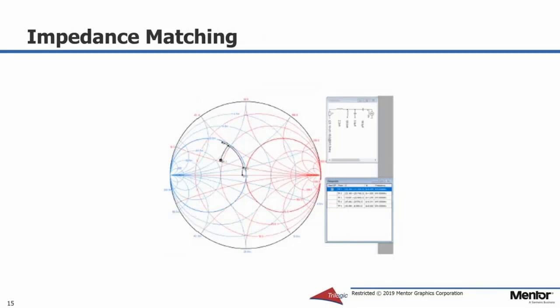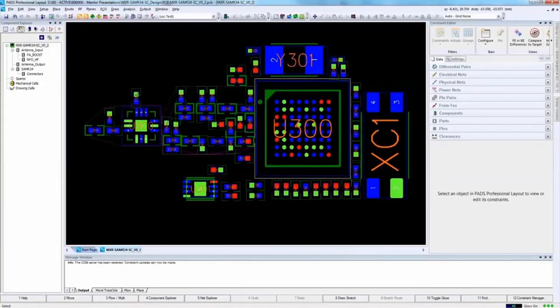Impedance matching in required areas of the design must be adhered to for optimal results, especially between the radio IC and antenna. Here's a layout where we have functional blocks. The antenna switch block you can see in a purple outline. I'm highlighting the front end block here.